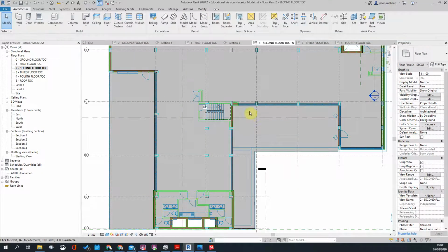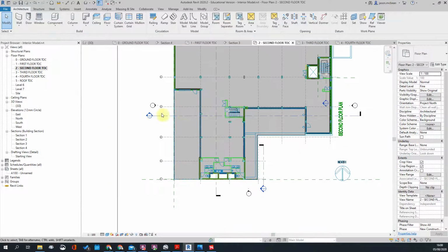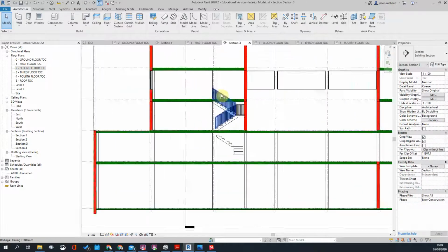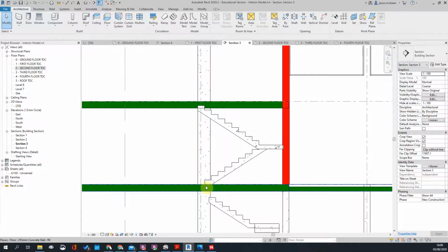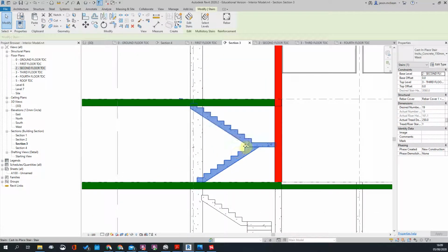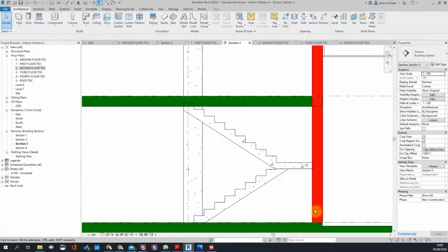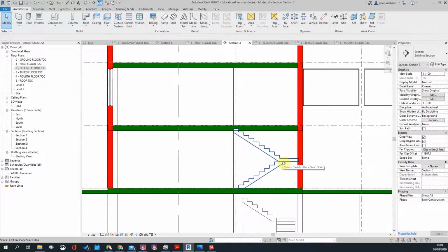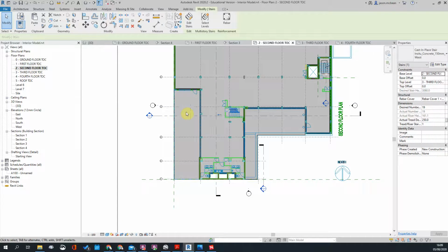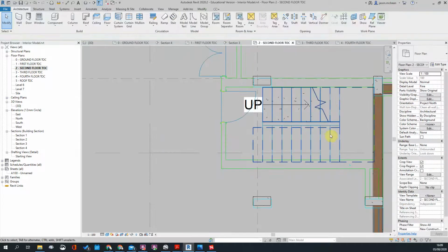You can see the doors, these things need to line up, otherwise the shaft does not work correctly. So we're going to have to make some amendments to this. The stair goes up and it ends at the wrong place. I'd much rather have these start and stop in the right place and have an extra landing on the ground or at the top. So in this stair, let's quickly fix that.